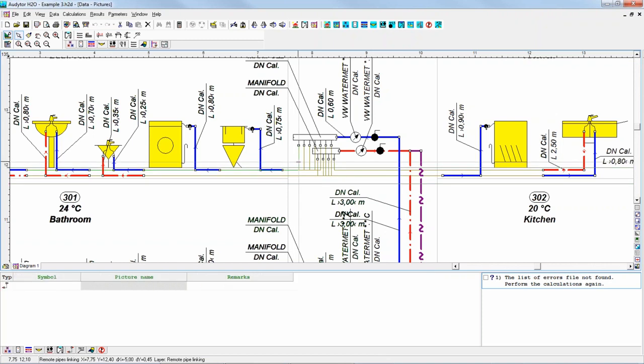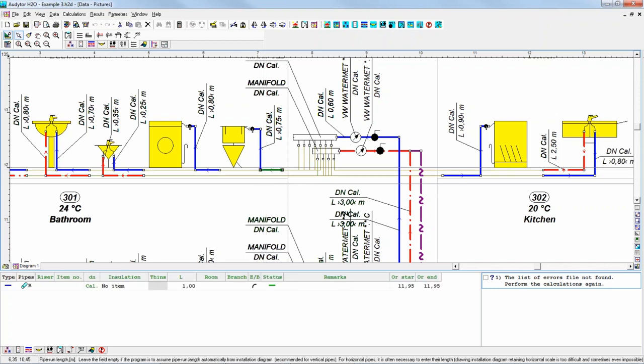And then we connect these pipes with so-called connectors of distant pipes. And this is the way of designing the manifold systems. Just note that for this element, connection of distant points, the program appropriately takes into account the vertical length, the length between the outlet of the distributor and this point in the floor. However, it doesn't include any horizontal length, but all the horizontal length must be entered here. It's 1 meter, for example, here 2 meters, and so on. You have to write it appropriately.